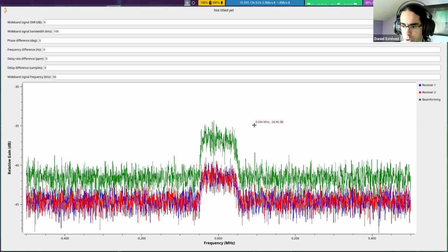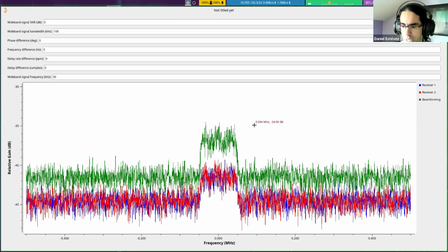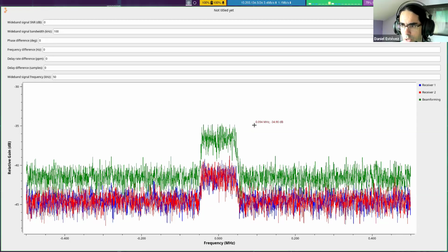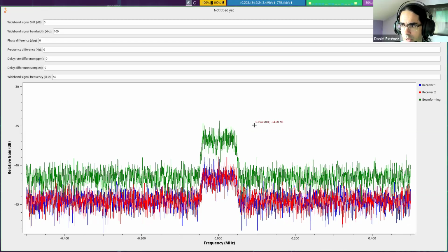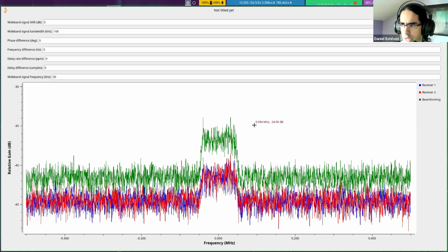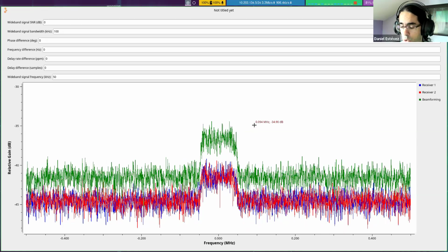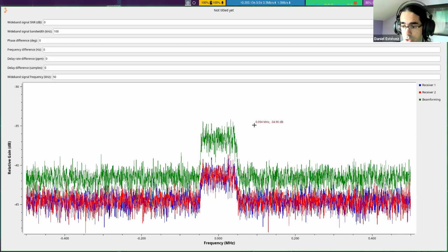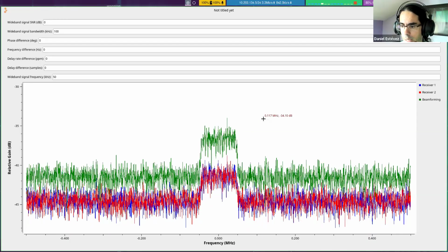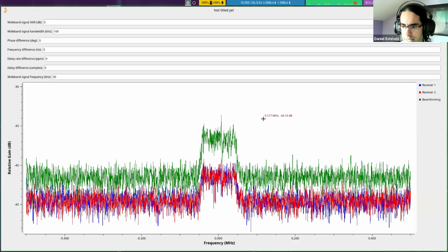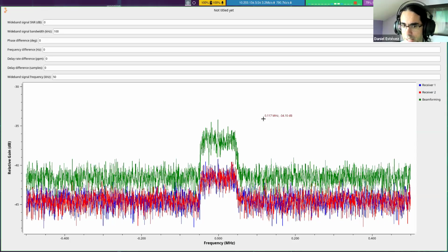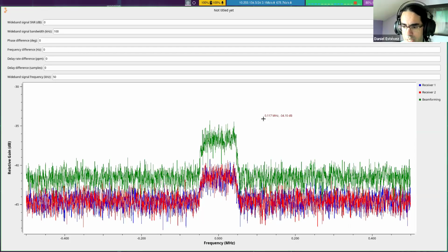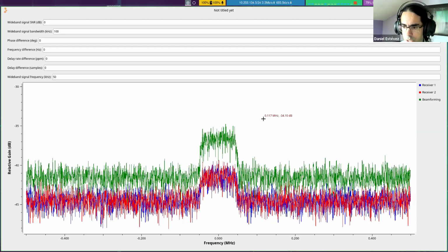And you could run the same numbers for many antennas, maybe 42 antennas like the Allen Telescope Array. So if you add 42 antennas together, then I don't know how many 42 is in decibels. I guess it's something like 16. So you would get an increase of 16 decibels of SNR compared to receiving the source on just one signal. So that's how beamforming works when the signals from all the receivers are aligned in phase, in delay, in frequency, in everything. Now we will look at what happens when they are not aligned, but before that, any questions?